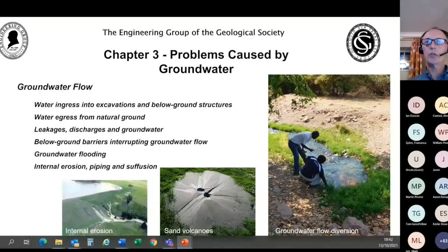The image on the right is taken from a dam in Zambia. During construction in the mid-1970s, it was noted that new springs of hot water appeared in the river channel downstream of the dam. This led to concern about the stability of the dam, and additional measures had to be put in place, including these relief wells and a stabilising berm.